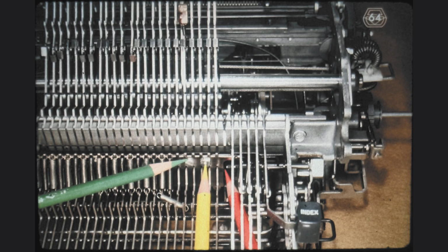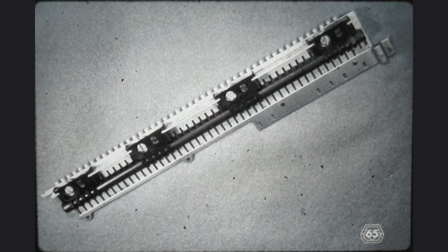We should never attempt to loosen this nut, unless we happen to want to separate the compensator tube from the rear interposer guide cone. The head of the screw whose nut we saw a moment ago is visible here, holding the clamp which ties together the tube, the cone, and the protective shield. As you can see, there are 4 of these screws in the compensator tube assembly. The only way we can gain access to these screw heads in order to retighten them is by completely removing the compensator tube assembly from the typewriter, as was done here. Notice also that the parts of the compensator tube assembly are not made of particularly strong or thick metal.